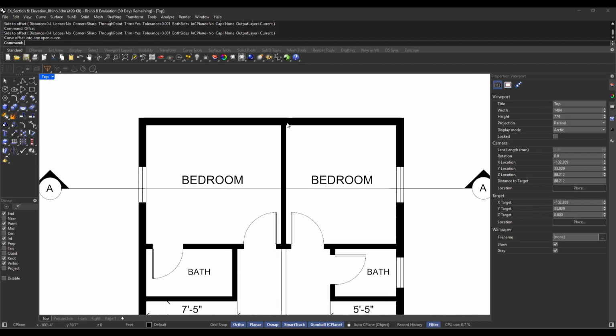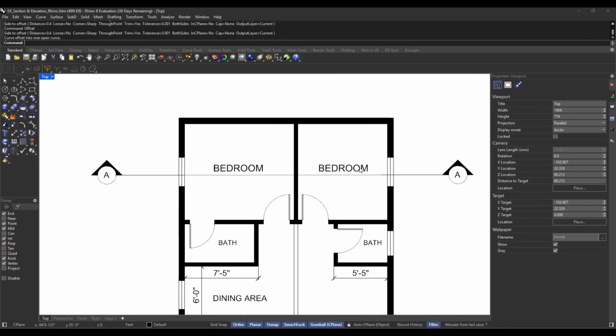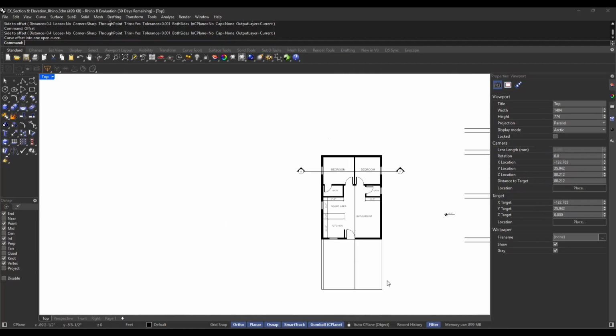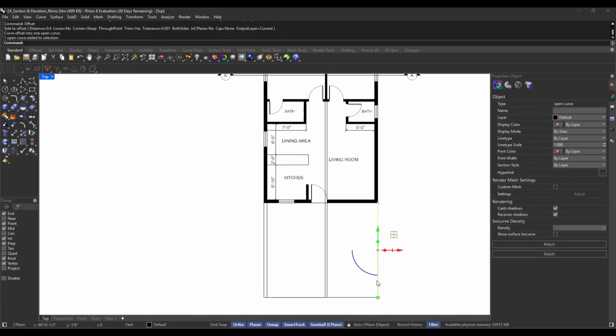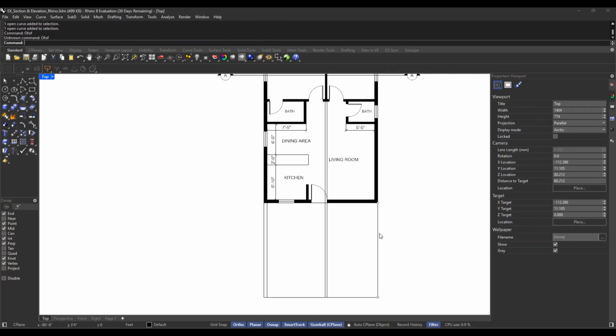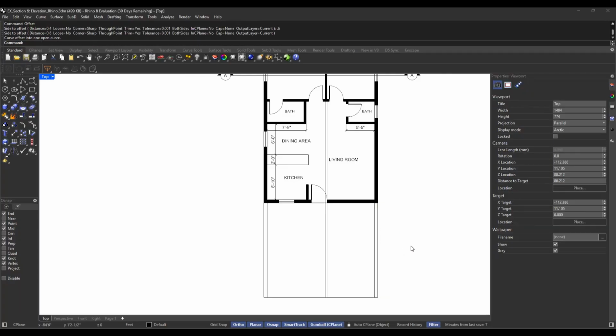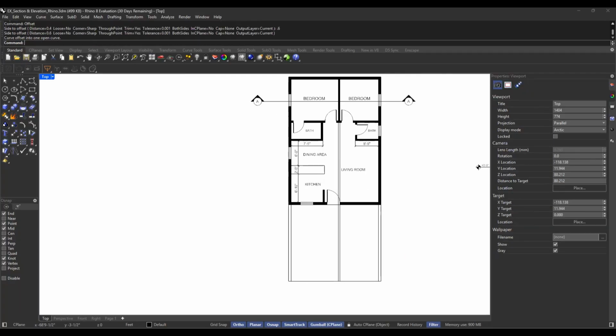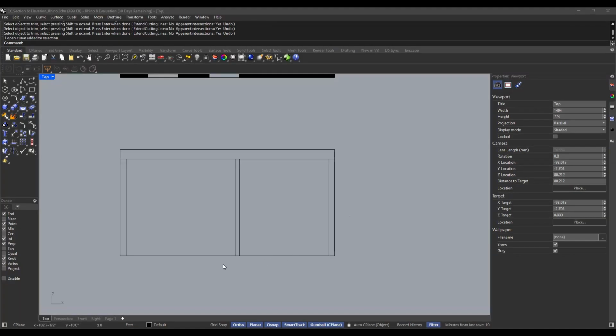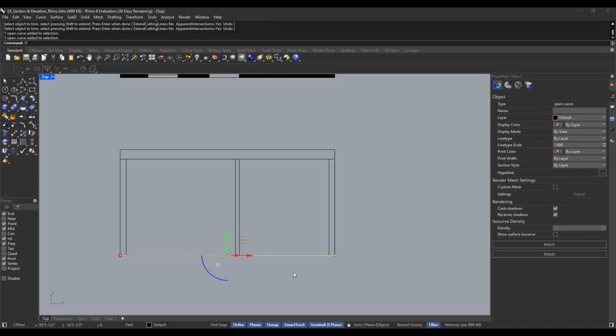And then we'll see the next is again the wall. So we see one line here and one line here, right? And then here we do have a window. Again, I'm gonna offset this, and there were 6 inches inside, right? And here you have a ground or floor line, so I'm gonna offset 6 inches as we had in SketchUp.